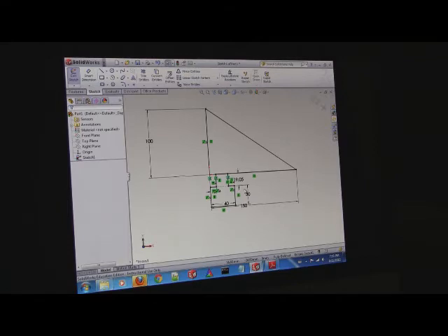Okay. Now, go ahead and dimension that one to 40. Yeah. So you can either select the points or you can select the line. It's one less click if you do the line. And then select that line is 30. This one should be 40. Okay. Now hit escape. Drag that line down until it's the right geometry again. Okay, cool. Now dimension that line to be 19.05.